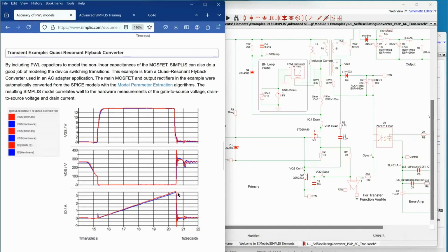So you can see we get really good fidelity and accuracy. You can see the little Miller thresholds during turn on and during turn off. The fact that the turn on threshold is higher than the turn off, even though the current is essentially 0 during turn on and 3.5 amps during turn off, this negative difference suggests that the gate resistance is quite substantial.